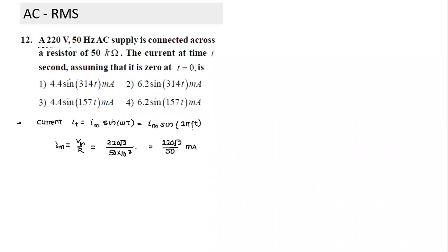So whenever we apply Ohm's law, whenever we write the equation V equals IR, we use either the RMS values or the instantaneous values, and both have to correspond. Since I'm interested in finding the max value, the corresponding V value also has to be the maximum value.